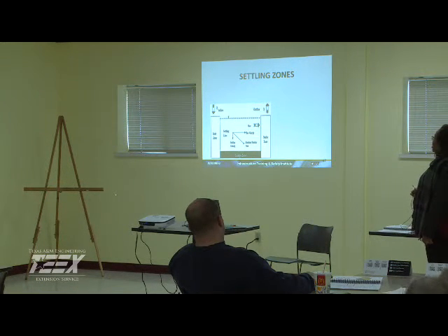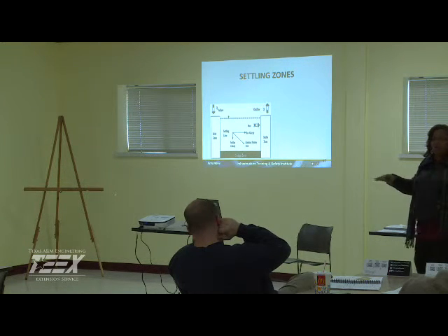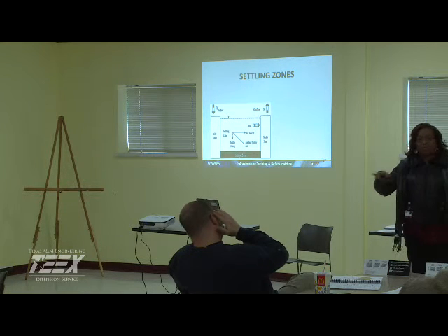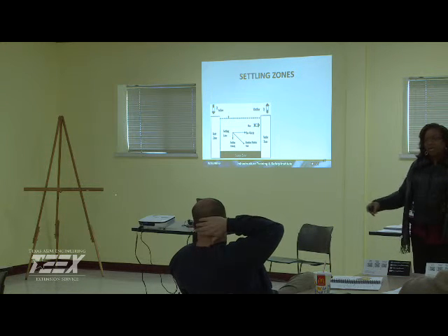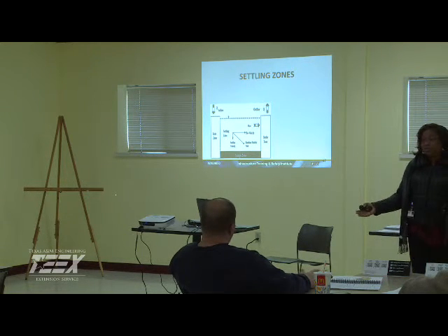Another slide talked about the settling zone. With the settling zones, we have an inflow coming into the plant, which is considered the sedimentation basin inlet zone. Then you have a zone where settling occurs, where the flow is equally distributed over that basin. Particles that are heavy enough will settle out, and that's your settling zone. Then heavier solids fall to the bottom, creating your sludge zone.